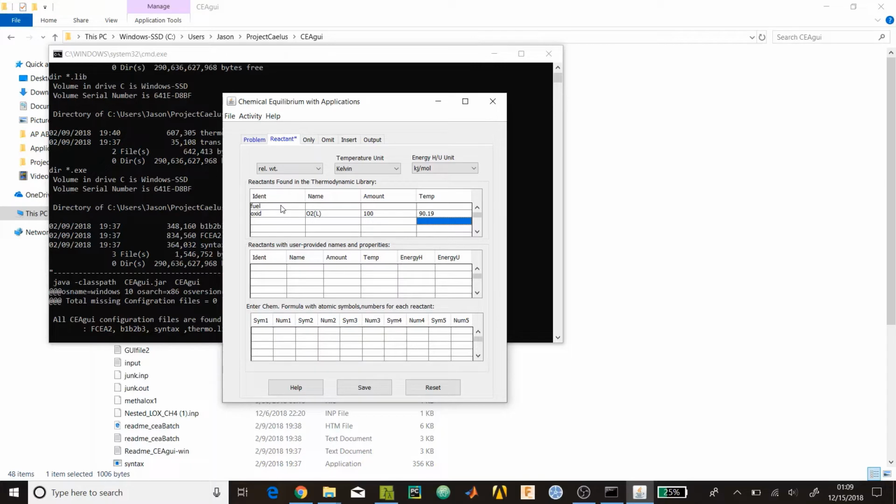And for the fuel, we looked into a bunch of different fuels like hydrogen, methane, ethanol, RP1, and just kind of did the pros and cons of those fuel combinations. The space shuttle uses hydrogen and liquid oxygen, but we're definitely not using hydrogen because even though it gives higher efficiencies, higher specific impulses, its boiling point is like 20 Kelvin. It's way too cold for us to handle, so we're not using that.